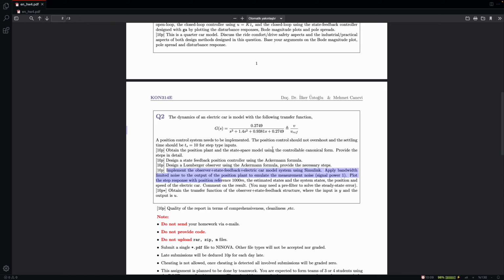Okay, so why do I force you to use the transfer function? Because then it would make sense why we use the observer. Of course it should work, so validate that using another Simulink model, but here in the final image I want you to have a transfer function up here, some additional stuff here, band limited white noise and stuff, and then the output, observer, then the state feedback controller connected to each other, and then that is generating our input signal.